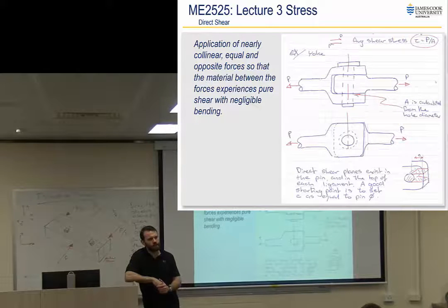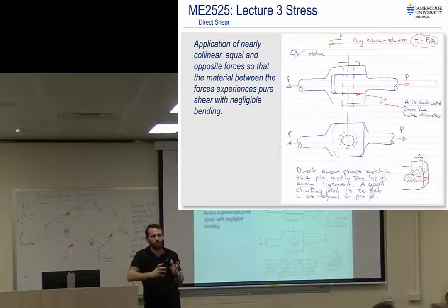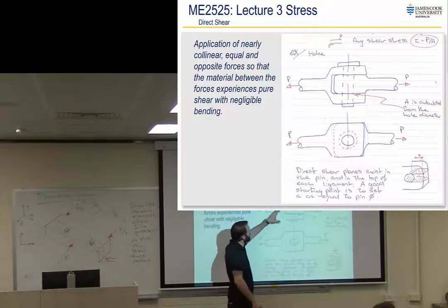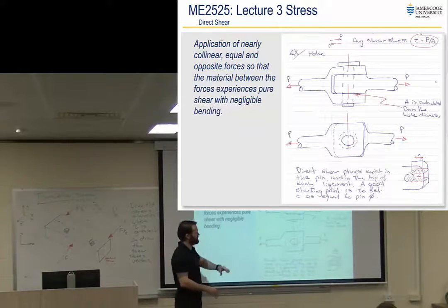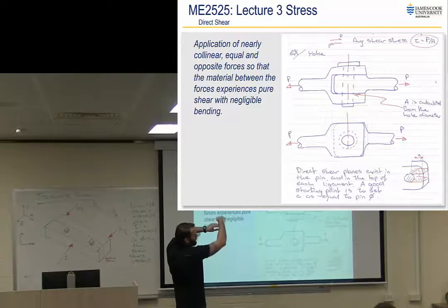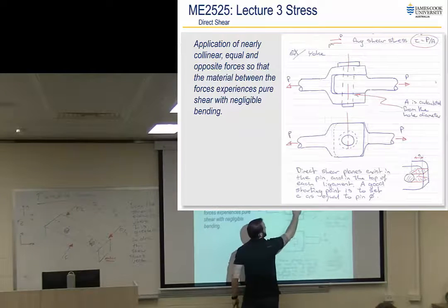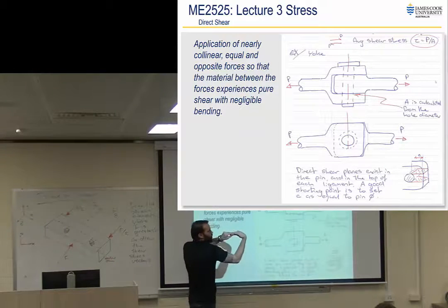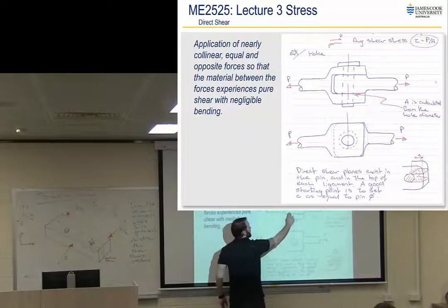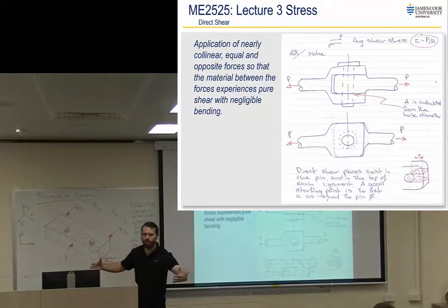It's an example where you know where that transverse shear is carried throughout the entire cross section? This is where the actual geometry of whatever componentry you're doing isolates the shear to a single plane. All right, and so this yoke is a good example where hopefully that's a two-dimensional drawing, but you can understand that the left-hand bit of the yoke's like that, and the right-hand bits of the yoke's like that, and it's got a hole through it and a pin that goes through that centre. All right, and so the fact that if there's small tolerances on that gap and that gap, that force P is being carried by that pin just on that singular plane there and that singular plane there. All right, it's not being distributed over any particular distance.